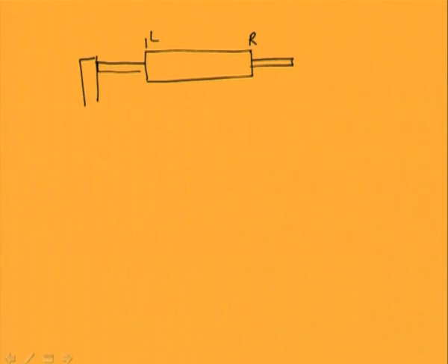So once we have explained the procedure of the influence coefficient method, let us see what instrumentation is required for this purpose. I will draw the line diagram of this, and I will also explain how to measure the phase. We have a rotor like this, in which we have left and right planes, these are the correction mass planes, and this is the bearing which is supporting the rotor.